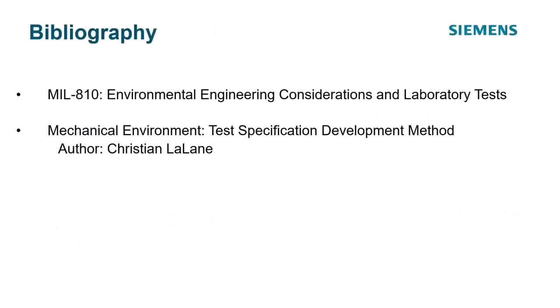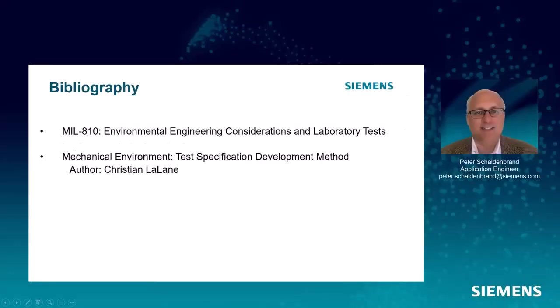So, mission synthesis. There are 2 documents that this presentation is taken from. The MIL-STD-810 has a lot on developing tests. And then there's Test Specification Development by Christian Lalanne. Most of our software is patterned after that text. It's a 5-part series: sine, random, shock, FDS, and specification development.